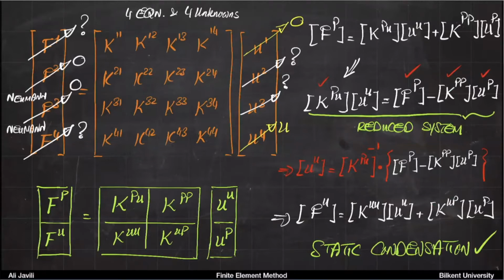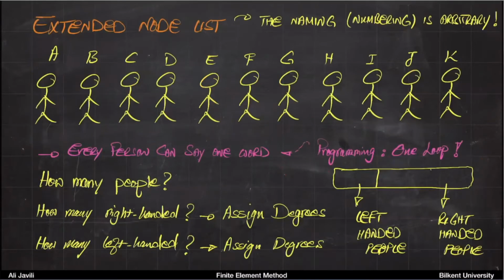So if you solve your reduced system, then you compute all the displacements, and that is exactly the main part of the finite element method. Also, in a post-processing step, usually, if you want, you can calculate the unknown forces. Okay, but that is pretty much a choice. So the first part is what we need to do. That's the most important part. And then we had this new question: how can you sort these degrees of freedom so that they do that? And then we learned that by a simple example.